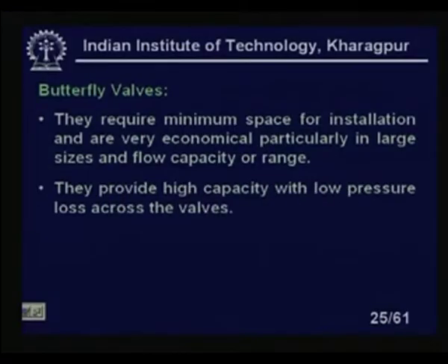There is no such seat or plug in the case of the butterfly valve. That is a great advantage, which leads to a higher range of the control valve. They provide high capacity with low pressure loss across the valves.